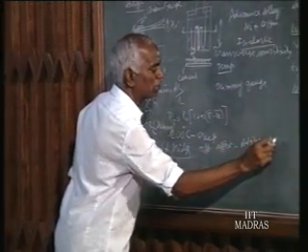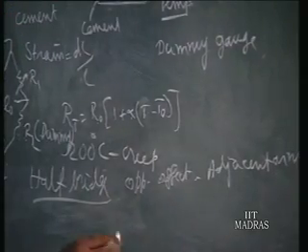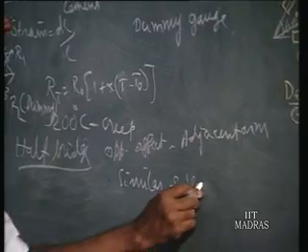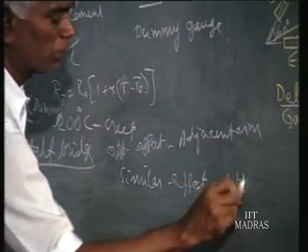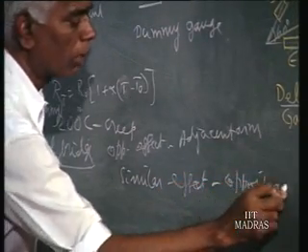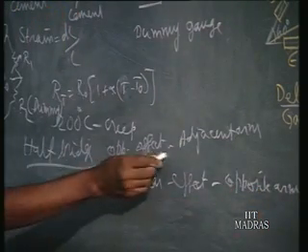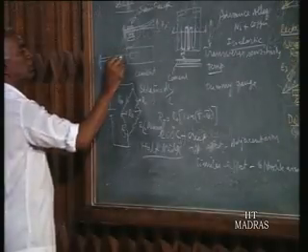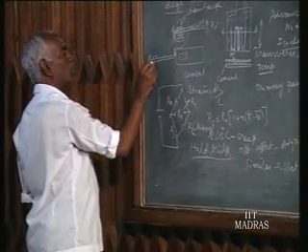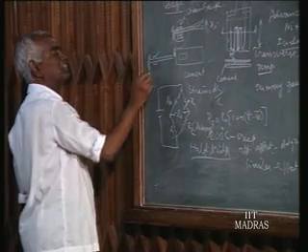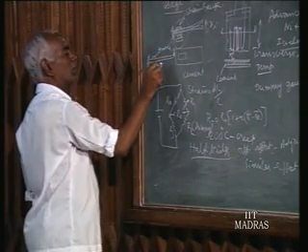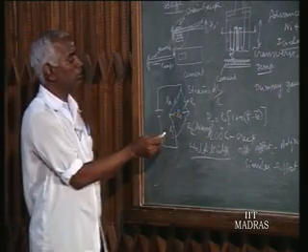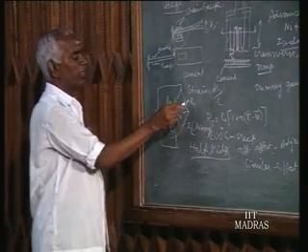When we have the similar effect, that is similar effect that we have learnt under the bridge network, similar effect in opposite arms of the bridge. But when it is opposite effect, that is a cantilever, for example, opposite effect is there in a cantilever, we have learned. So this is what displacement is given. One is top, one is bottom. So here tensile strain, and here you have got compressive strain, that is opposite in polarity, and these two strain gauges are connected as adjacent arms. In this case, the temperature is similar effect gets cancelled automatically.